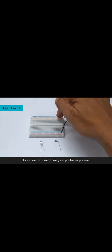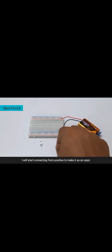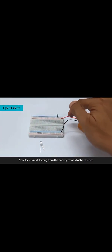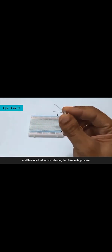As we have discussed, I have given positive supply here, so the line which is in horizontal connection will all get positive voltage. Similarly, the negative will get negative. As we know, the current flows from positive to negative, so I will start connecting from positive. To make it an open circuit, I'll first connect one resistor from the positive supply, somewhere here at the center. Now the current flowing from the battery moves to the resistor and then to one LED, which has two terminals, positive and negative. I'll connect the positive side to the positive side.